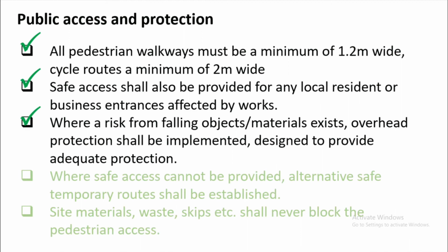When you have an excavation on the sides of the public, you need to make sure that there is also protection on the perimeter of your excavation, so that people will not fall into your excavation, especially at night when there is no light and the people are already tired, so they are not alert to see your excavation. So make sure that all necessary controls to protect people from falling into your excavation are provided.